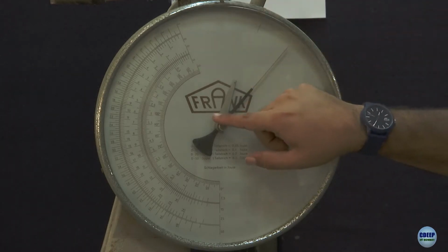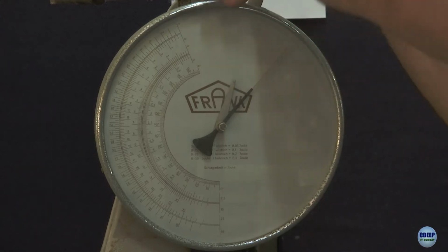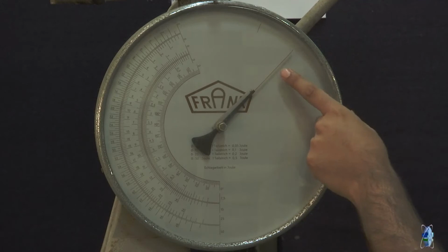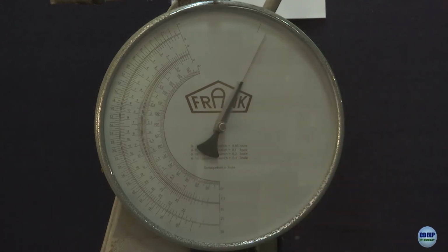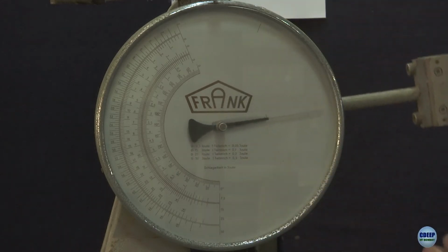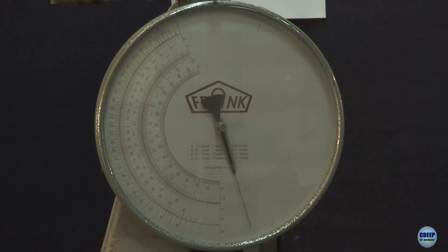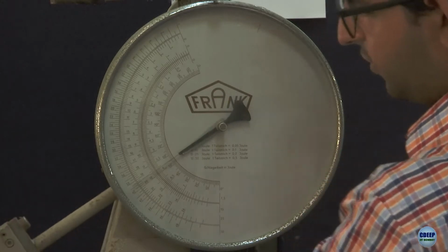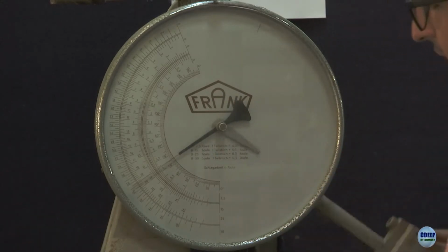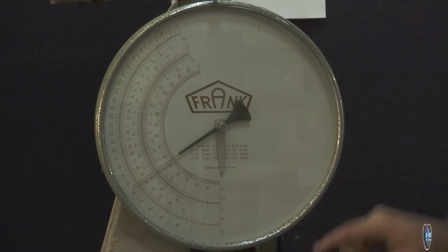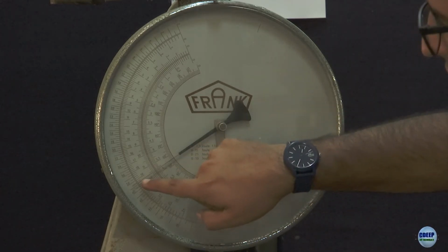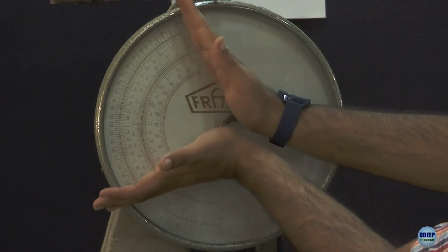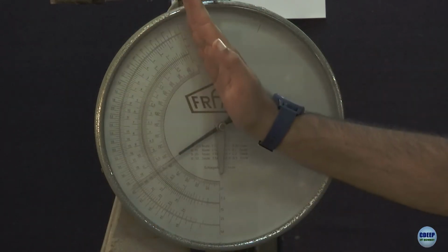So what you see here, you can see this moves. It contacts the blade. The blade starts here. When it moves, it contacts the blade and pushes the blade. If there is energy loss at this point, and let's say it only comes up to this point, then it will swing back. So what we notice is the blade gives a reading of certain joules. This sector here is the energy lost. If there was no energy loss, basically it would have come all the way up here, but it has not.